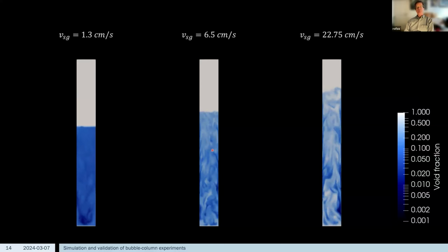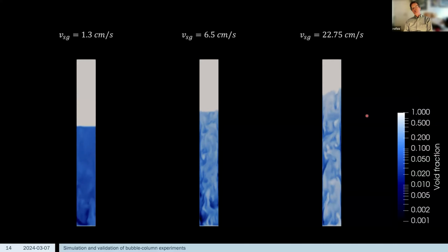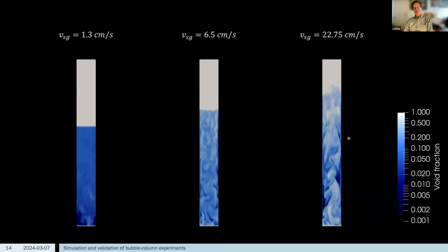So it's kind of quite dynamic, and then as you go up, the flow becomes more and more dynamic as you see basically buoyancy-driven flow, where the light flow goes up very quickly and you get very fast down-moving flow at the walls. And in the movie that I showed you earlier, you could see this too. You can see it's quite dynamically different than the homogeneous case.